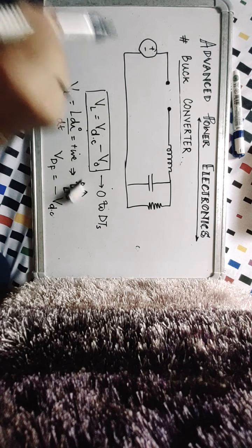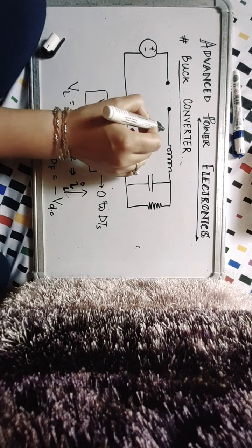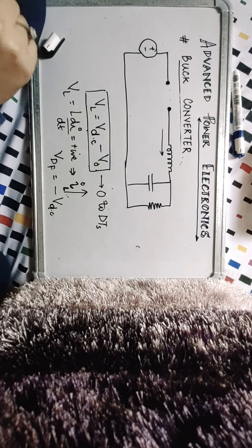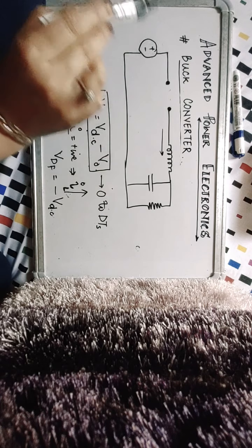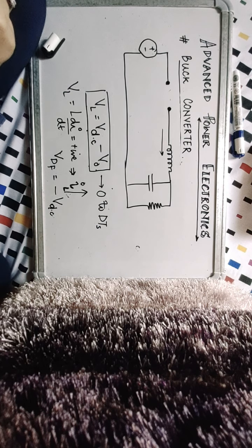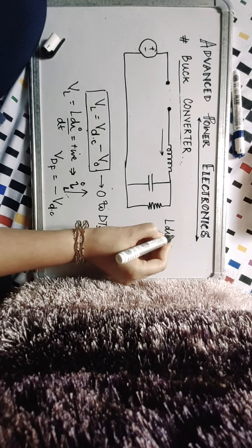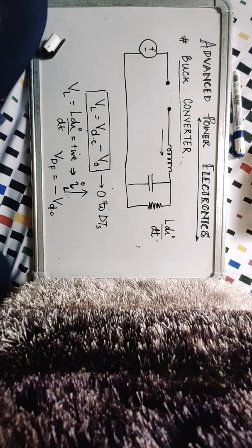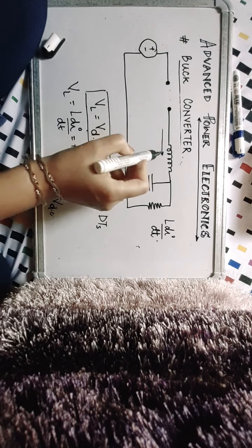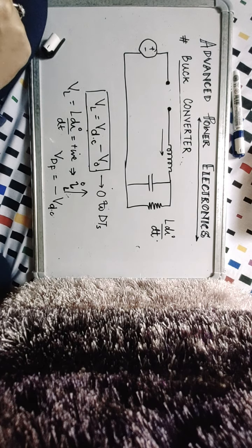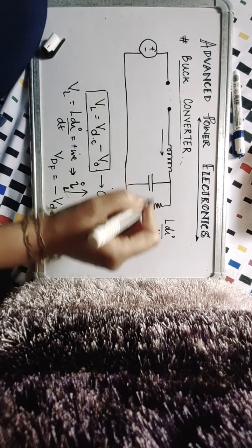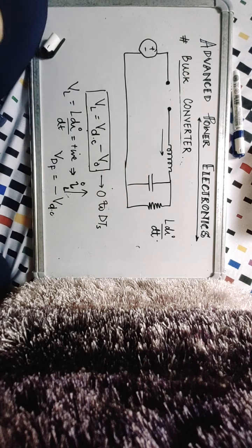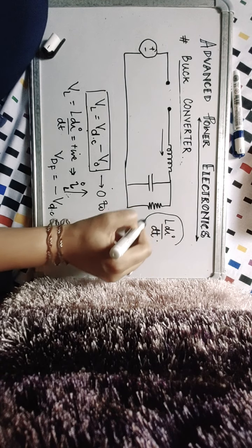So suddenly it looks like you interrupted the current flowing through this inductor, which had been rising previously, and suddenly it got interrupted because the switch was opened, which means that there is a sudden L di/dt kick or a sudden L di/dt spike. There are many ways of seeing this. The inductor had stored energy previously. Now you already know that an inductor has no net energy consumption. If it stores some energy, it will have to release that energy back. Or in other words, if you try to interrupt the flow of current through an inductor, it will always disallow it by inducing an L di/dt kick.